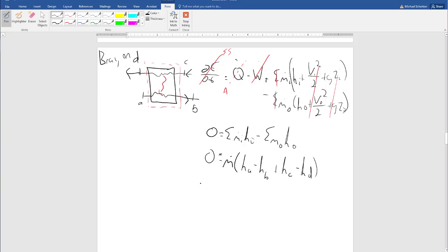And then typically, maybe you'd use this. The other equation you might get here would be the regenerator efficiency, which would be the heat that's actually transferred divided by the maximum heat transferred. This is talking about the heat that goes from the hot to the cold. So here we're going to look at the cold side, the actual transfer.